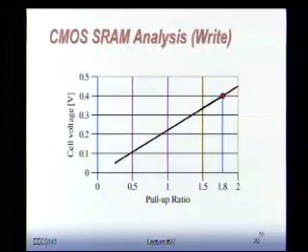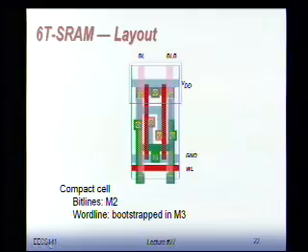And this is a simulation again of the right condition. In this case, we only look at the PMOS case, and you can see that if the PMOS would get too strong, we will basically get a cell voltage which is going to 0.4, and we're basically toast again. So this is typically how it would look like.